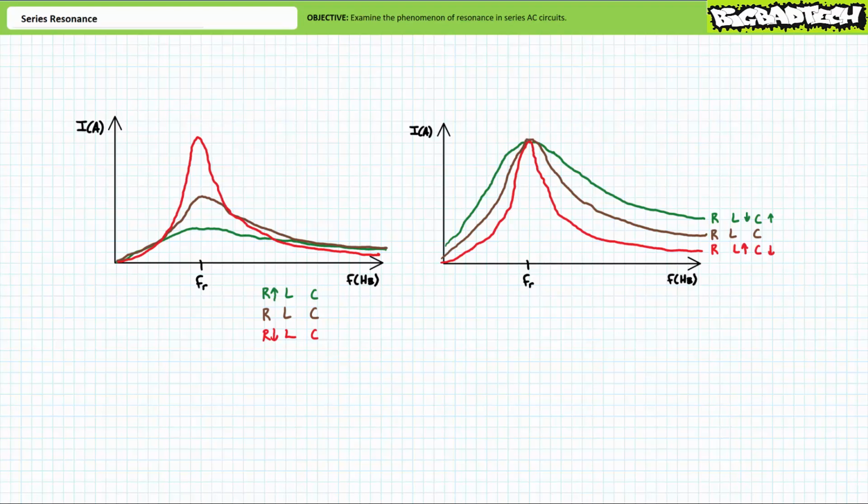Have fun. In conclusion, this lecture examined fundamental properties about series AC resonance. We learned series AC circuits experience resonance at frequencies when the capacitive and inductive impedance components cancel each other out. At conditions of resonance, impedance magnitude valleys, and source current peaks. Additionally, we examined the significance of the quality factor on the selectivity of a given circuit and examined the means of calculating bandwidth and half-power frequencies. Remember to review these concepts as often as you need to really drive it home.